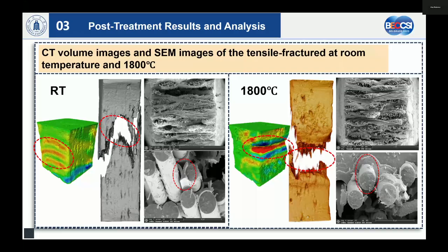In contrast, the significant lateral strain bands in the DVC results at high temperature correspond to the necking phenomenon of the sample until fracture.